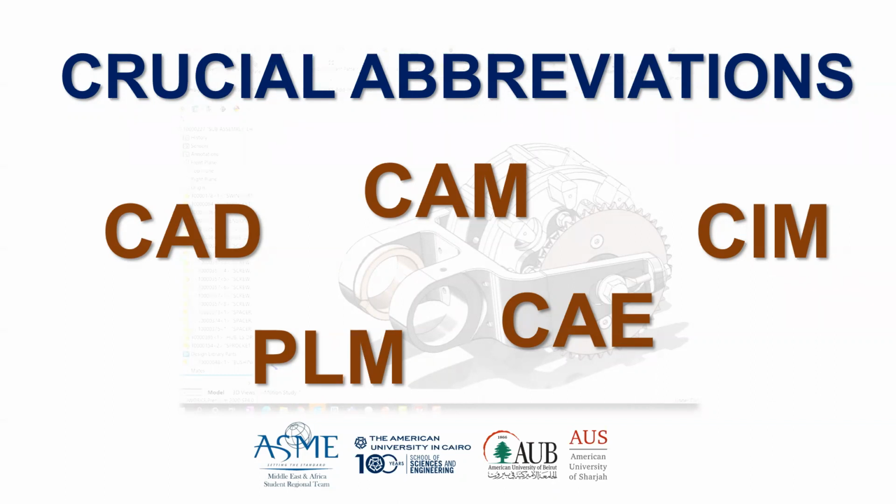Moving to the second one, which is computer-aided manufacturing. Actually, this abbreviation is related to something called CNC. CNC stands for Computer Numerical Control machines. The manufacturing machines are dealing with computer programs, okay? So we have a CAD model or a CAD file, okay? And then you're translating this CAD file into something like a code, so this CNC machine can translate this code and do the manufacturing process of this component. This is called the CAM process, computer-aided manufacturing process, okay?